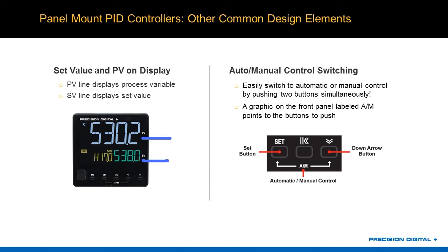And so you can see in this case, my process variable isn't quite at my set value. Looks like I'm off by about 8 degrees, and so it's not very far given we're talking hundreds of degrees. And as I'm approaching that set value, my manipulated value, my MV, is getting low. My heating output is only 17% because it's going to slow down to just maintain that temperature at what it needs to be to keep that 538 degrees.